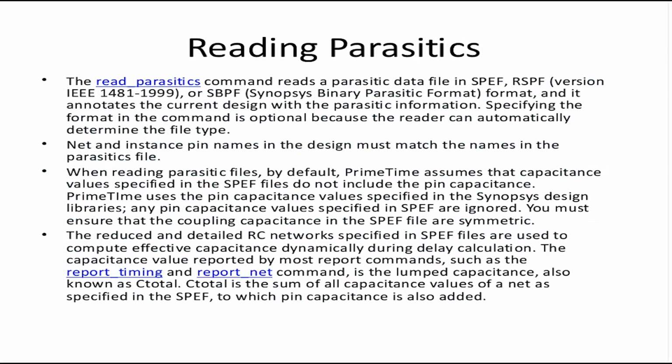The reduced and detailed parasitic RC networks specified in the SPEF file are used to compute effective capacitance. We'll talk about what effective capacitance is. This is a part of delay calculation. The capacitance value, this is the most important thing.